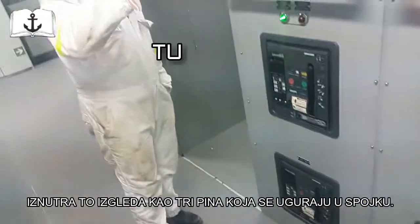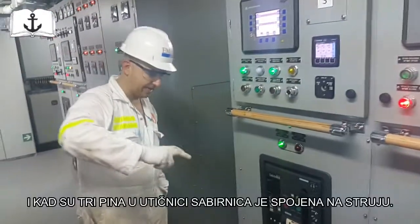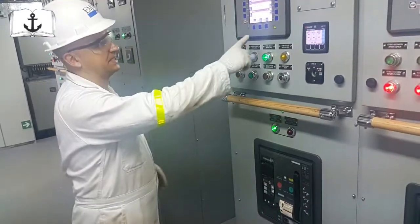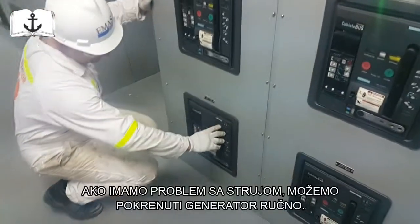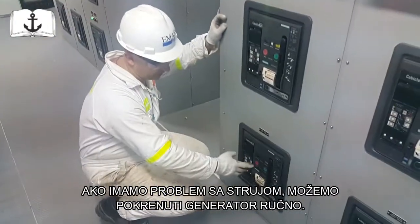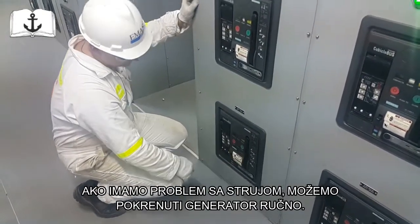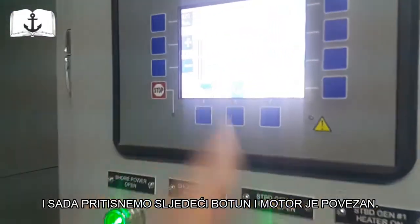You have 3 big pins. These are the fuses with the tulip connections, they call it. There is a chassis inside, it's moving, and they enter the sockets and connect the busbar. And now I can always do it manually also. You have the lever here. So if there is any mechanical problem with the breaker, we always have the possibility to, like we call it, pump it mechanically. And then we push the button. And now it's connected.